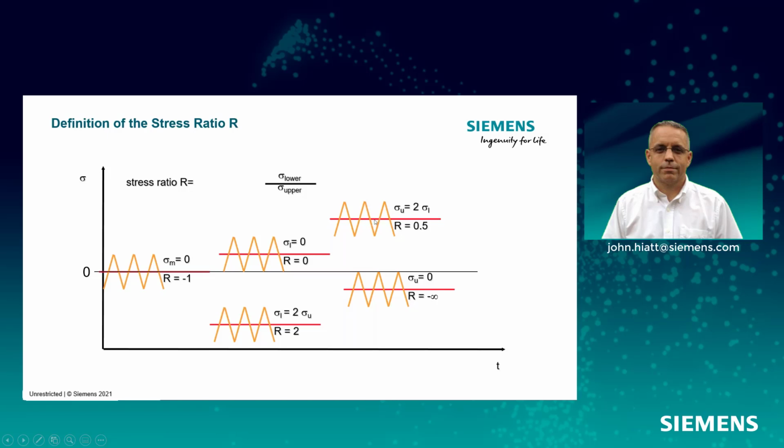Generally, if we're talking tension compression, this is tension, this is compression. If we were talking about shear stress, we have no negative. It doesn't matter which way you load it. It's the same. It's symmetric. So when we get SN curves, we need to understand this R ratio, what it is. It'll be specified. When you see -1, it's called completely reversed loading, zero mean. If you get zero, you have a positive mean.